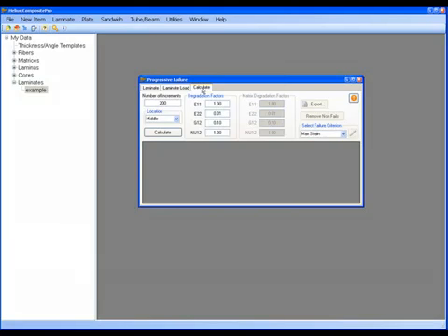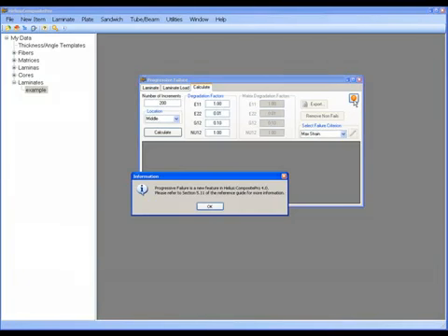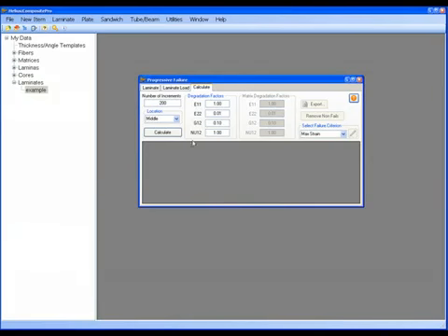And now as I go to the next tab, I see some new options here. On the right hand side, we have a new screen. It tells us this is a new feature in CompositePro 4.0. Number of increments is new to you. That is the steps in which the CompositePro will step through to get from 0 to 200 KSI. It shouldn't surprise us then to see these steps in 1,000 PSI increments.